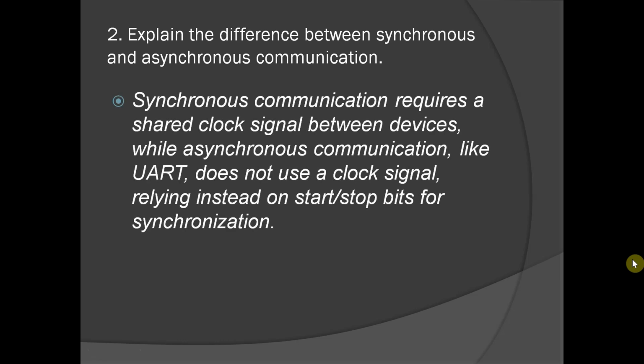So synchronous communication requires a shared clock signal between the devices, while asynchronous communication like UART does not use a clock signal, relying instead on start and stop bits for synchronization.